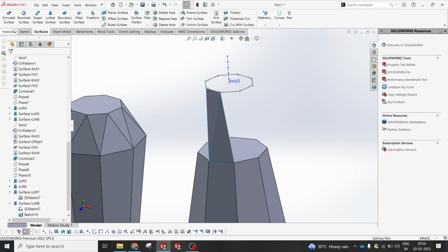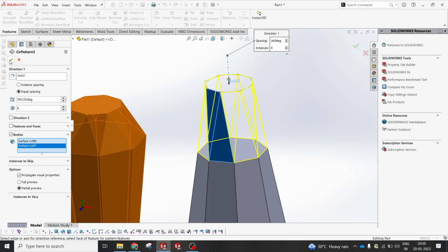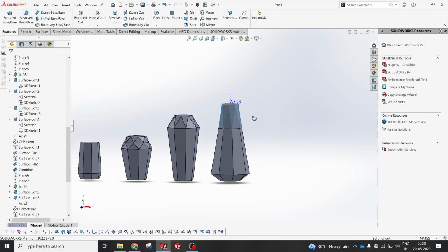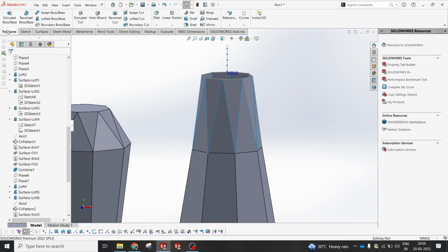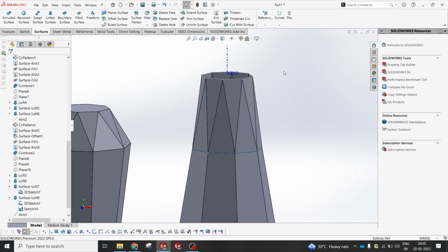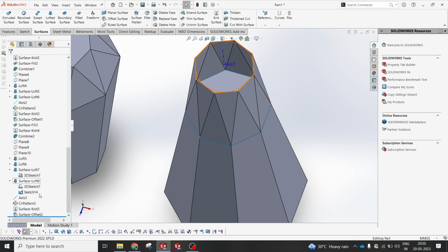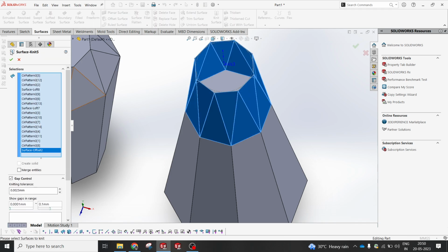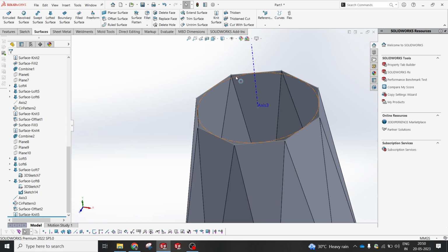So I will go with again a circular pattern by having this body, this too. Yes, perfect. Looks good, right? Okay, so surface, net, select all, good to go. Mesh, and again select this, offset 0, and better to knit with this. Yes, perfect. So again we are saving another set of steps now.